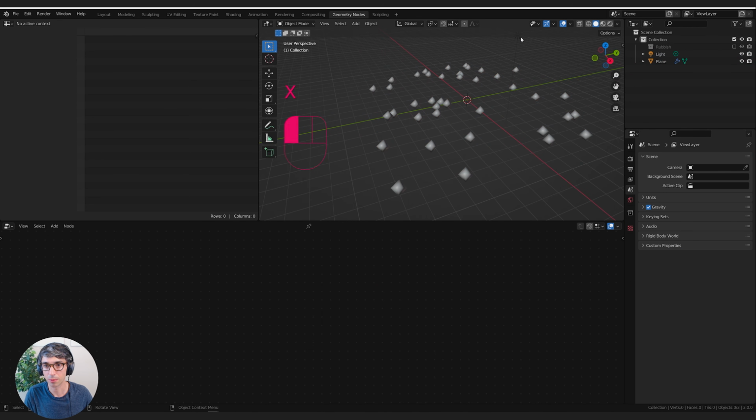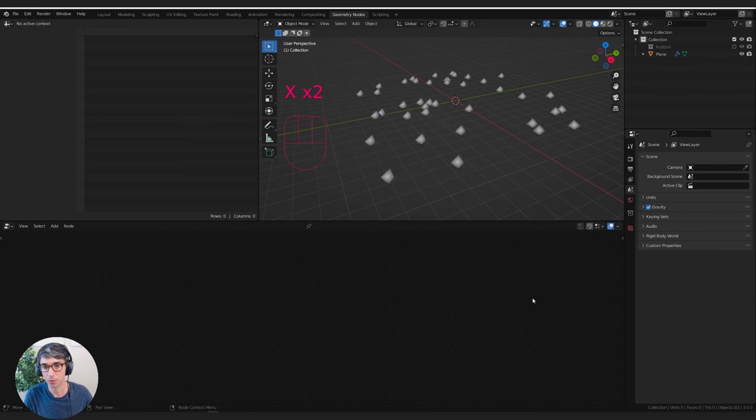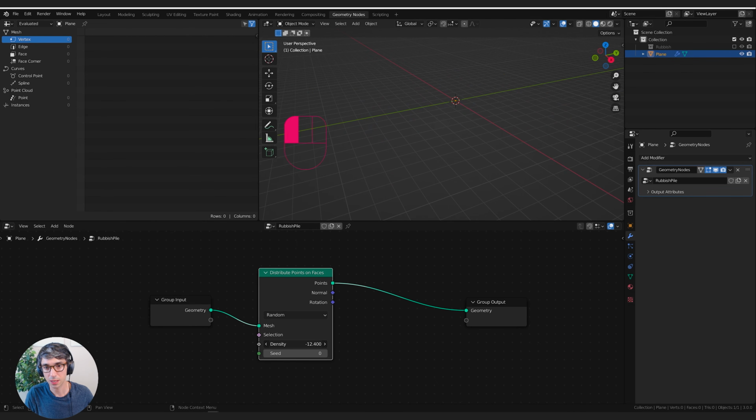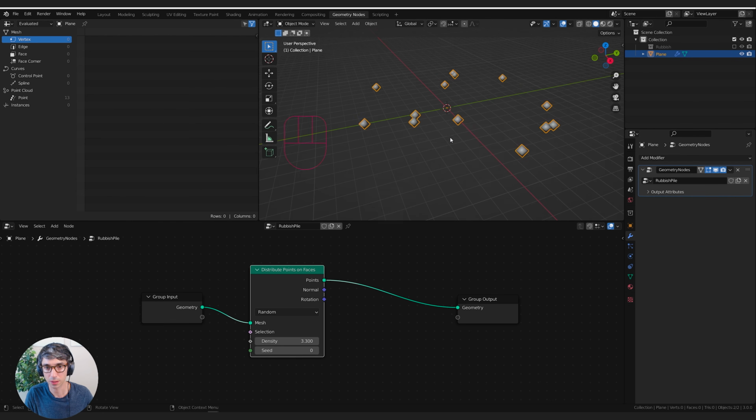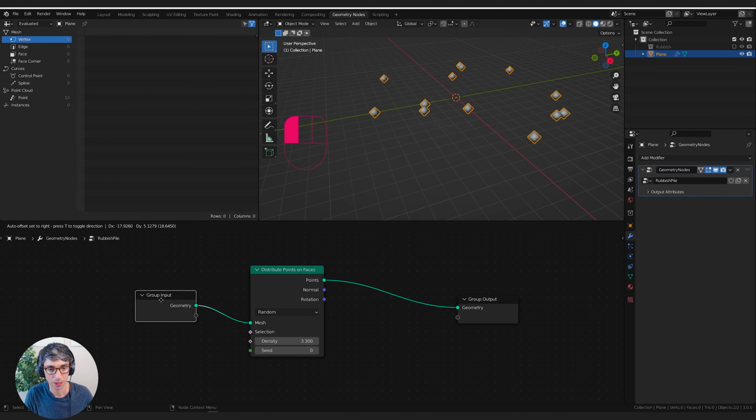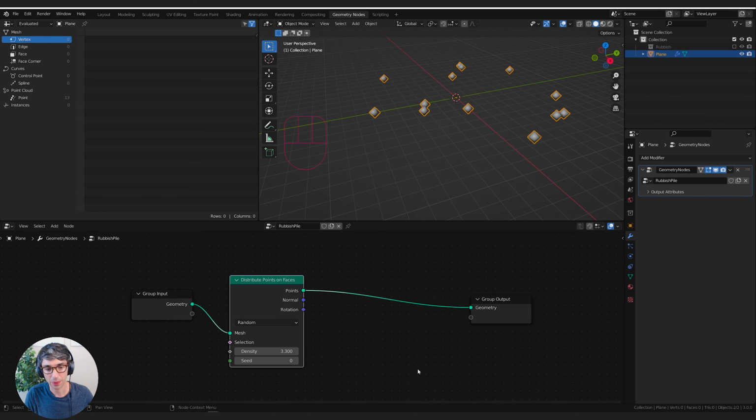the surface. I'll just clear that camera and the light so it's not in the way for a bit. I can increase the density, and I'm just going to leave it kind of low for a minute so it doesn't get too dense in case it breaks Blender or something. Now, once I've done that, the next thing is I need to instance geometry where those points are located.